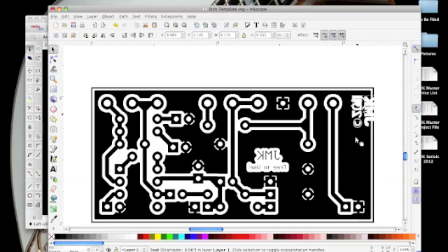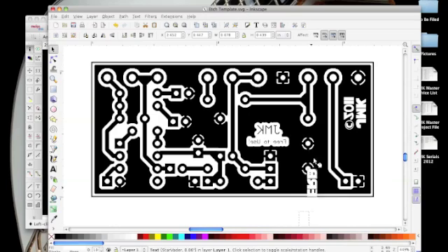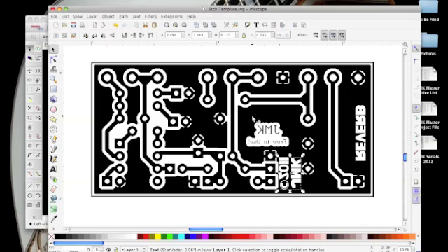Now what I've got here is a couple extra little things. One is a titling ability for the actual PCB, and the other one is sort of a copyright logo. Now I've already got JMK right there, and I've also said it's free to use, so I really don't need a JMK copyright 2011. Notice there that it's actually flipped around. I've reversed it, right? So this is how it would read normally. What I've done is I've actually flipped it over so that it's backwards. That's important for when you actually etch. Everything you write on your PCB here has to be flipped backwards. If it doesn't get flipped backwards, then it doesn't show up, right?